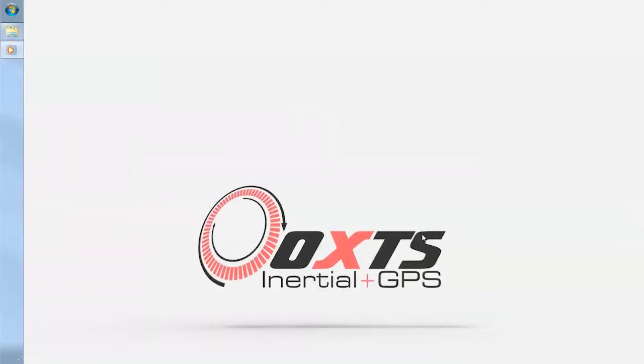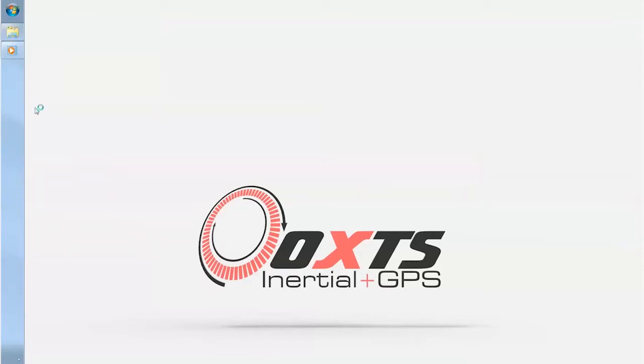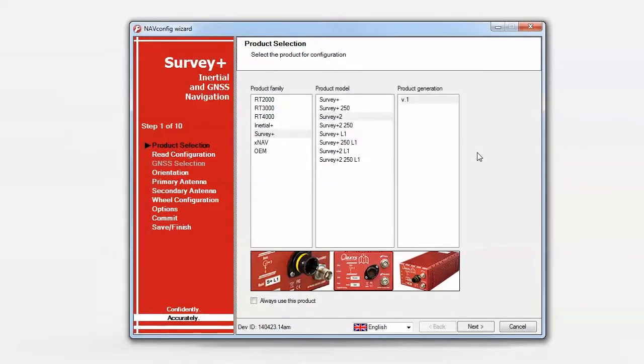Once the software supplied with your product has been installed, NAVconfig can be started by clicking on the Start menu, then All Programs, and scrolling down to the OxTS folder where you will see the program's icon. Although an Ethernet connection is required in order to send a configuration to your product, NAVconfig is actually an offline editor. That means you can create and modify configurations without having a live product connected.